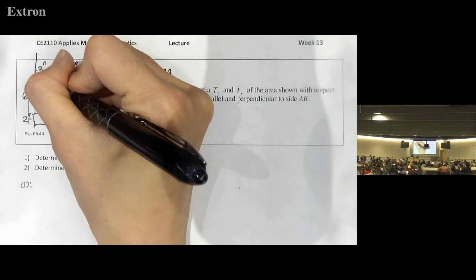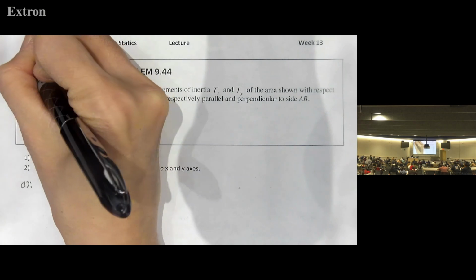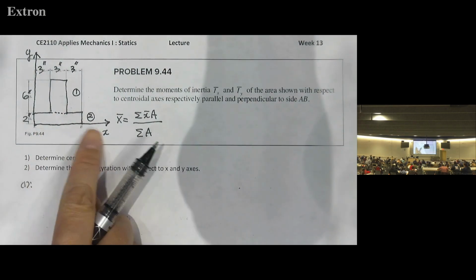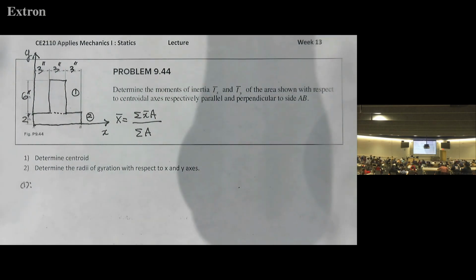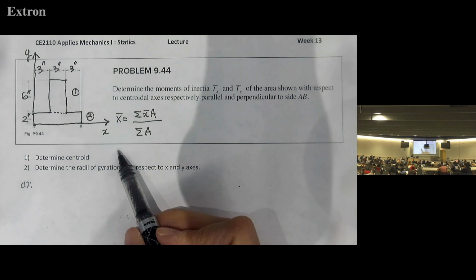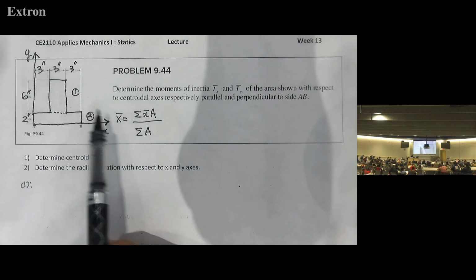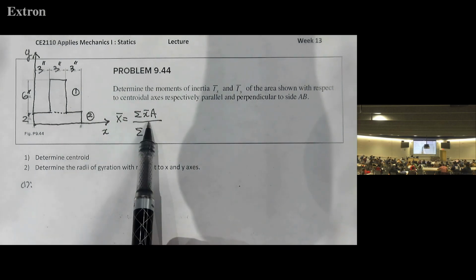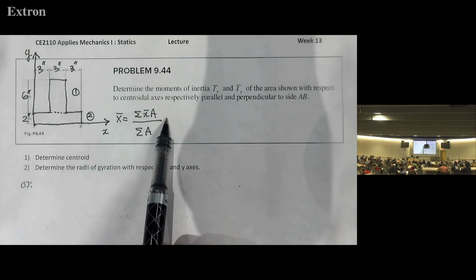And then the far left axis as y-axis. But these 2 lines are not the central axis. It's an assumed baseline, okay? You can choose any assumed baseline, but using that you can accurately calculate the centroidal axis from whichever axis you define, okay? It's a simple shape, so you can use this equation as is in the exam or homework, right?